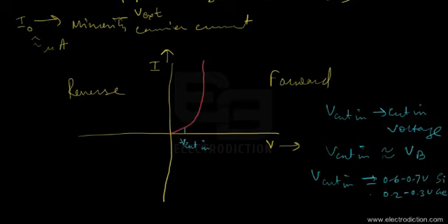Alright, so when the diode is in the forward biasing condition, we get the forward characteristics. Upon increasing the forward voltage across a diode, the diode current begins to increase but very slowly. There is no significant change in the amount of current flowing across the diode until the forward voltage exceeds the cut-in voltage, and when it does, the diode current changes significantly.